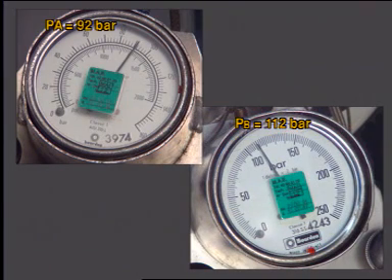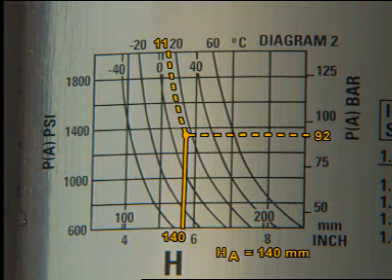Make sure that the difference in pressure at the top charging valve and the bottom charging valve is more than 10.7 bar, this condition being enough at this point. Using diagram 2, find the dimension HA for the pressure and the temperature at the top charging valve. Dimension H must be the same as HA plus or minus 1 millimeter.